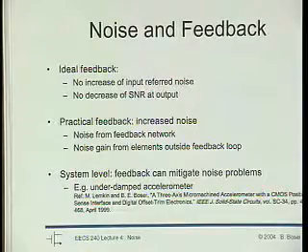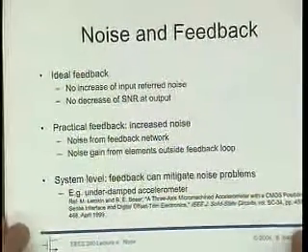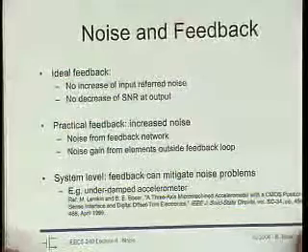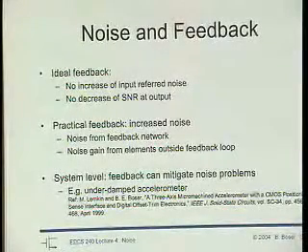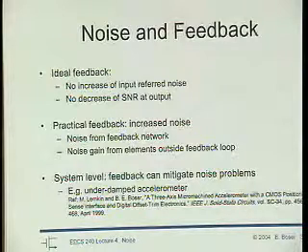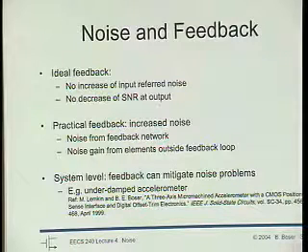That's only the ideal case, though. In practice, feedback usually increases the noise. First of all, we suddenly have a feedback network. I think I mentioned it once before: you add a device to your circuit, and it may do a few good things, but it's also an additional new noise source, and for noise it may do bad things. In the end, you may still win. The benefits may win out, but we now have noise from the feedback network in addition.